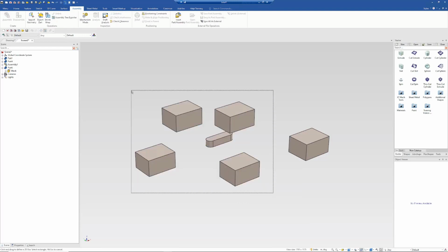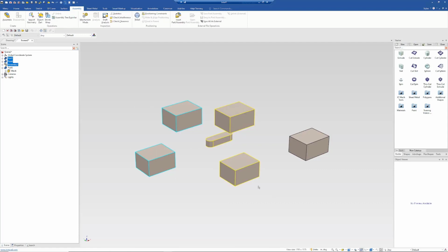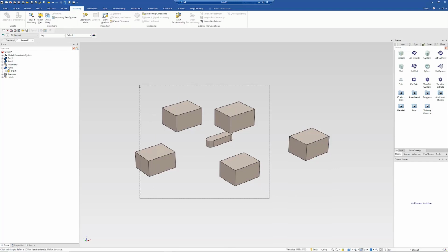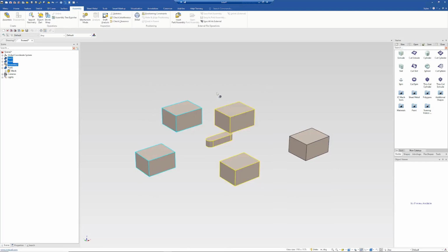But whenever you use the shift selection to select all your tools and you wanted to go back over and select even more to the list, you would remove anything that was already selected. So we've added new functionality that allows you to use shift and tab at the same time. So when you add anything to the box selection filter, it is only additive now. So when you do a box selection, you hover over something that's already selected, it will only add to your list.